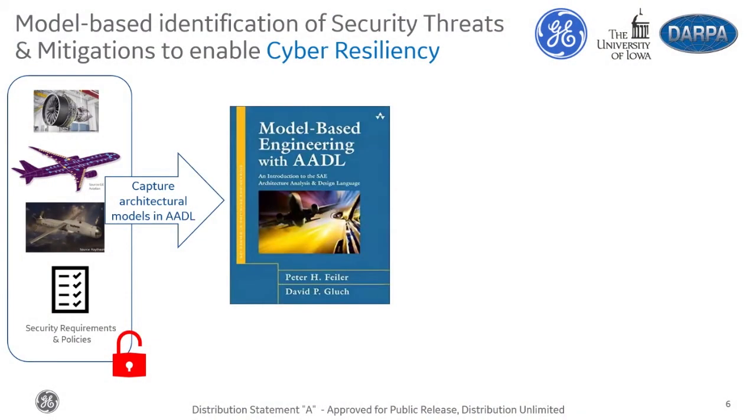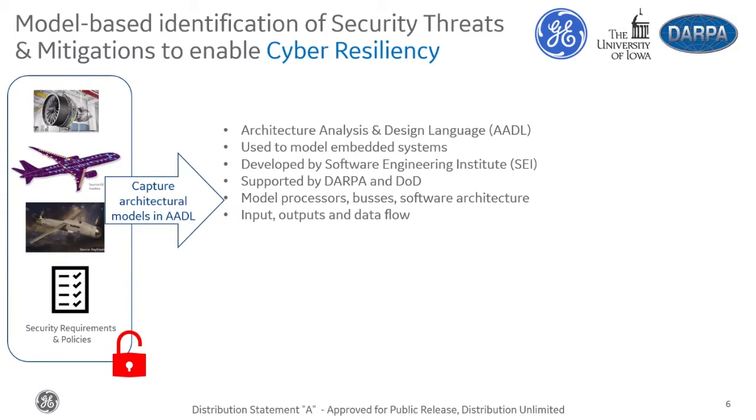I point people at this AADL reference for folks who aren't familiar with AADL, and let them know that it's a language used to capture models at the architectural level for embedded systems developed by SEI. We use the OSATE tool to edit the AADL. And we model processors, buses, the software architecture, all the major embedded system components. And we were concerned with all the IO and the data flow throughout the model.